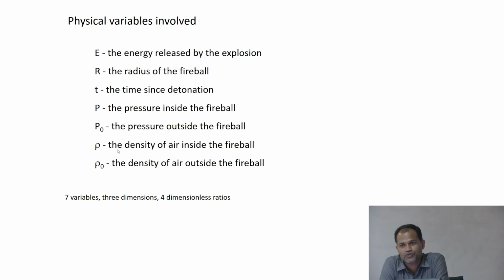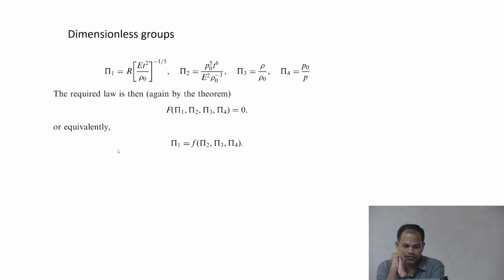Now you know how to do that because you know the Buckingham pi theorem, or you can use the Ipsen method. Find out what are the non-dimensional numbers that are going to come up. So that's the way Taylor chose to represent it, but you might get some combinations of these. You can actually verify that, as we said, it can be represented in many ways, depending upon what you choose as your repeating variables or what you select as your fundamental dimensions. You will get different combinations, but they would represent the same thing. So if you are getting, let's say, pi 1 and pi 2, if you combine pi 1 and pi 2 in some particular fashion, you are going to get the same non-dimensional number that he has written there.